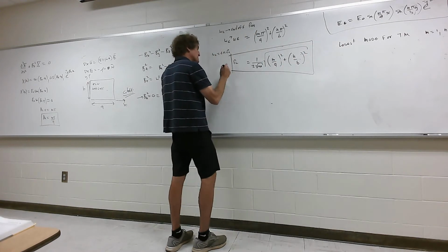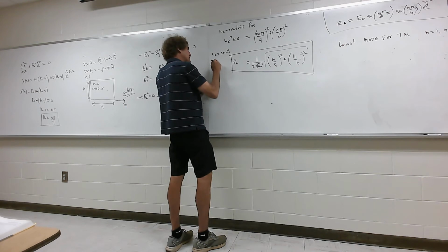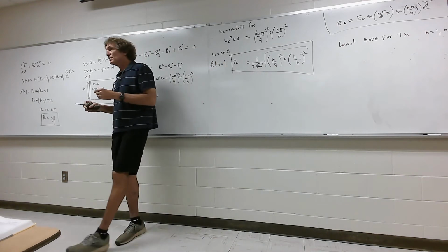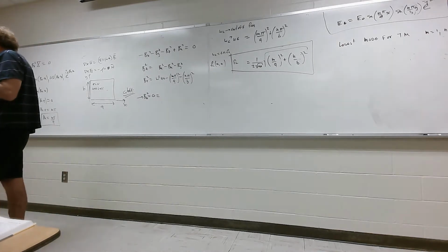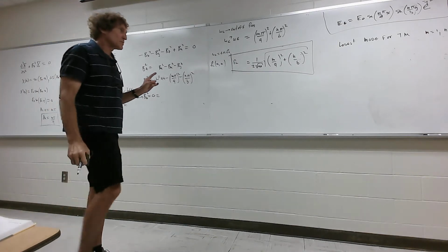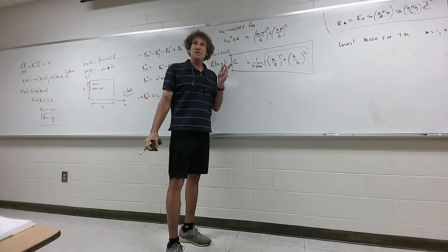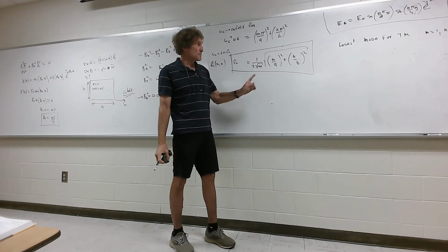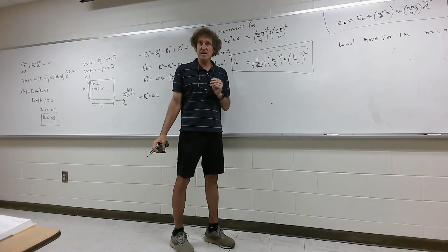But you're going to notice this, the cutoff frequency is a function of m and n. Y'all follow me on this? Now this will be the cutoff frequency for both the TE and the TM modes. I'm just telling you, the cutoff frequencies are the same. For a TM mode, the lowest frequency you can drive a waveguide in the TM mode will be the 1-1 mode, when m is 1 and n is 1. Do y'all follow me on that?